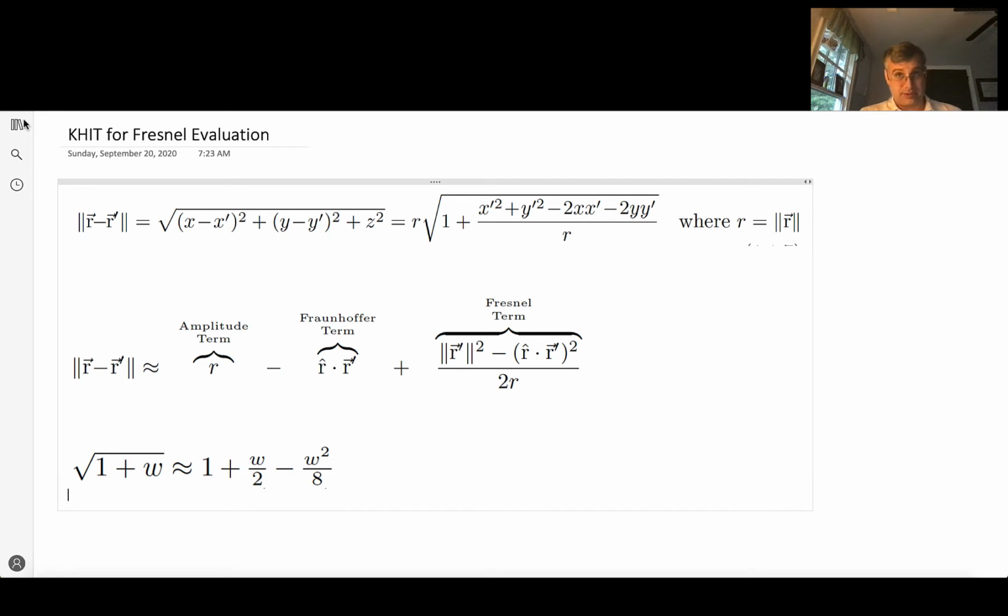What we do with that half plane then is figure out what the diffracting fields are, and this leads to one of the key results in electromagnetics called knife edge diffraction. It's a very practical formula. It has a lot of applications in designing everything from a point-to-point microwave link to optical diffraction at the nanoscale. So we're going to build that formula. That's ultimately where we're heading.